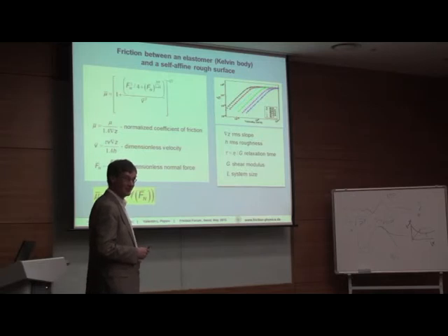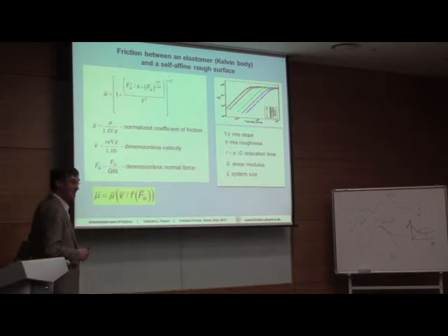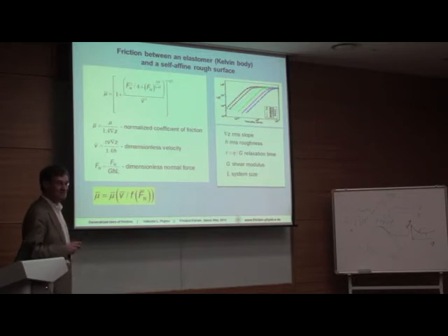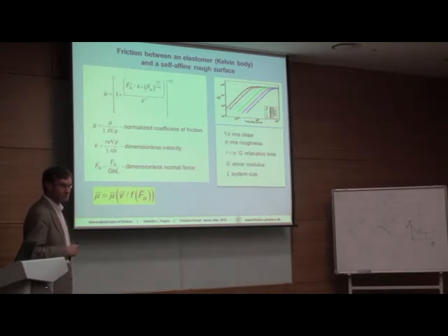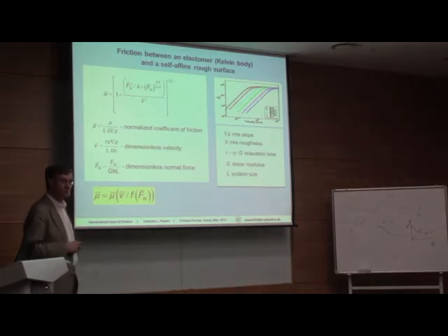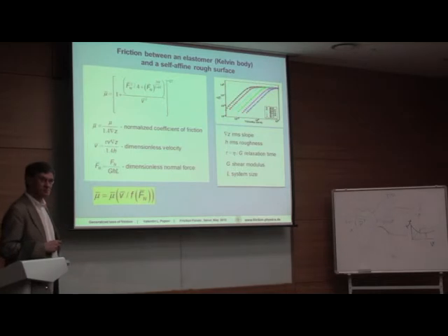Now, you know what's interesting? The vibration may come from the elastic recovery, because as the surface runs across the asperity, it can do two things. It can either shear it, so you've got debris and wear, or it can deform elastically, and that means it recovers. If it recovers, then like anything would, it would vibrate.